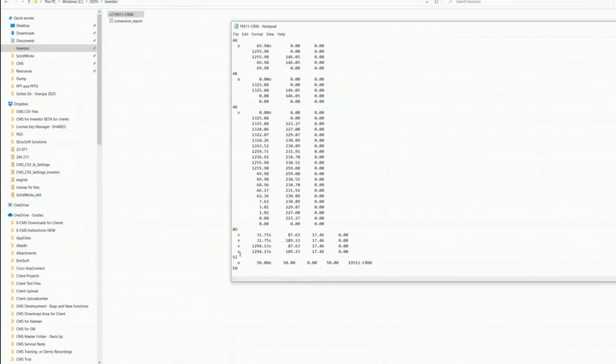If you just scroll down a bit quickly, remember that I said we are doing our stamping for the part number, right? We are grabbing that part number and we are putting it on a default position of 2 inches, which is 50.8 millimeter and 50.8 millimeter, and the height of the text is 2 inches as well, right? So what's going to happen? The machine will etch the part number on the top flange on that default location, right?